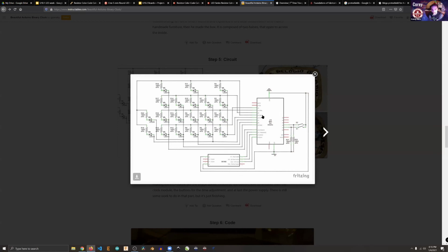And so this is a Mini Pro Arduino. This is just another flavor of Arduino that's small. And then how they connected all their LEDs. You can see it looks like they're using some of these as outputs and some of them as ground. And it looks like this is probably a Charlieplex set, just based on the way that they're attached. That's pretty common for how a diagram would look for Charlieplexing. So there's lots of interesting things to try and look at and make sense of.